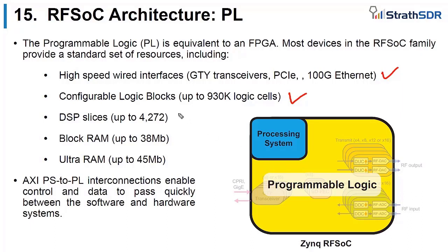We have a tremendous number of DSP slices, which are essentially evolved multiplier, multiply-accumulate units, in fact almost mini processors. If you go back maybe 25, 30 years, a DSP processor had one multiplier on the device. We've now got many thousands, clocking at gigahertz, so an unbelievable level of signal processing available. Hence, again, software-defined radio.